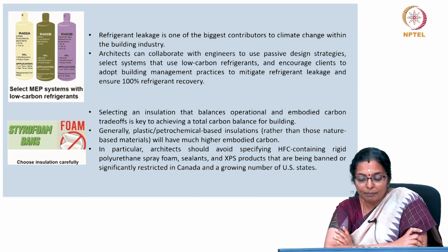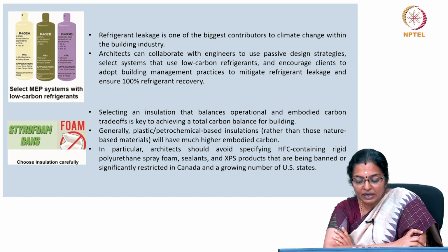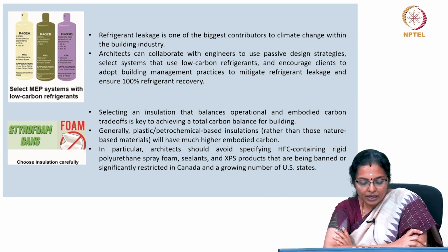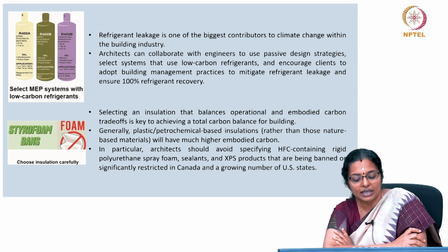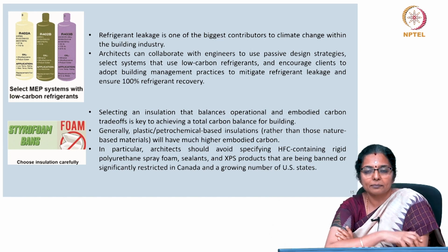Selecting an insulation that balances operational and embodied carbon trade-offs is key to achieving a total carbon balance for a building. Generally, plastics and petrochemical based insulation, rather than nature based or agro based, will have much higher embodied carbon. In particular, architects should avoid specifying HFC containing rigid polyurethane spray foam, sealants and XPS products that are being banned or significantly restricted in Canada and a growing number of United States.